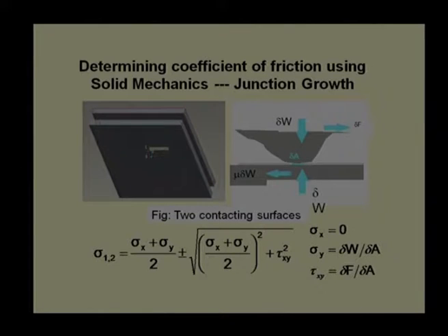If I simplify, assume there is a normal load only in y direction and in x direction there is no force, then sigma x will be 0, sigma y will be the normal force divided by the projected area, while shear stress will be friction force divided by contact area. These are the simple expressions. A more difficult expression can be achieved, but we want to find out initially with this approximate relation which can give some results close to the experimental results.